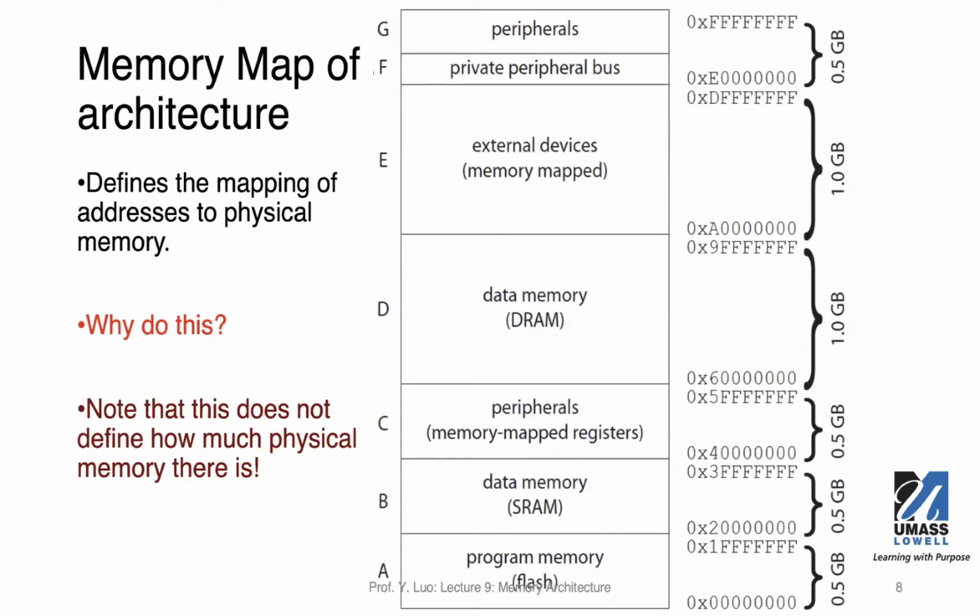So memory maps are very typical for all different embedded systems. We saw the example of AVR microcontroller earlier. This is an example, so don't take the numbers literally. In this example, we have a few segments in this big memory space. If you count from 0 all the way to 8 Fs, that's actually 4 gigabytes.